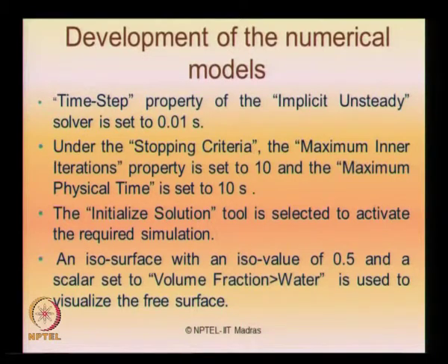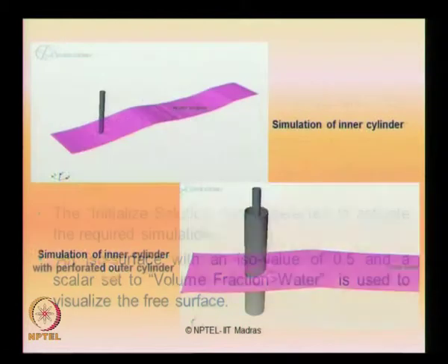The time step property of the implicit unsteady solver is set to 0.01 seconds. Under the stopping criteria, the maximum inner iterations property is set to 10 and the maximum physical time is set to 10 seconds. The initialize solution tool is selected to activate the required simulation. An ISO surface with an ISO value of 0.5 and the scalar set to volume fraction of water is used to visualize the free surface.